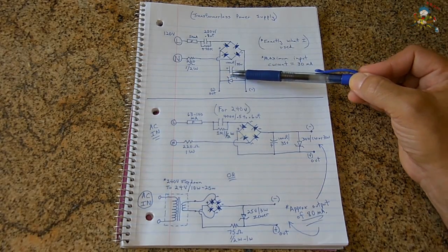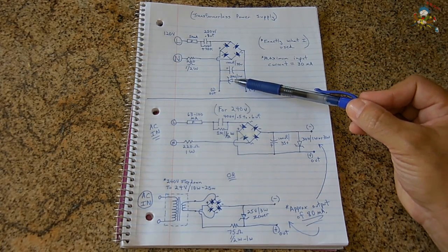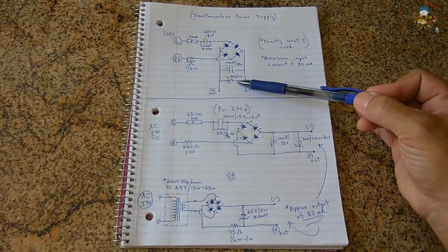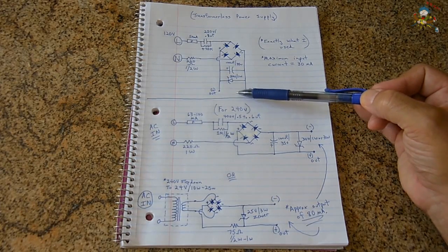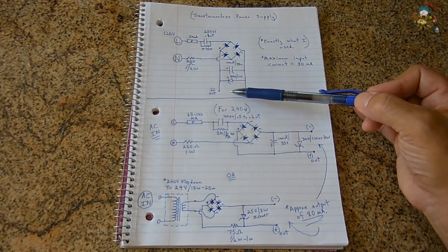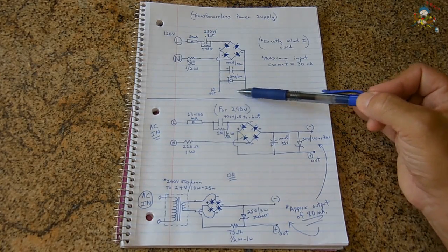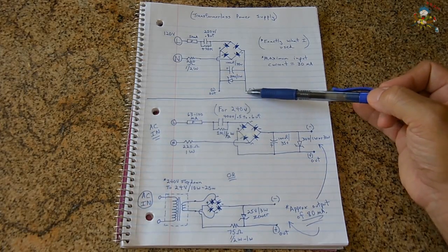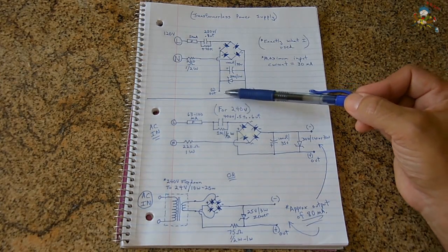Positive comes down, and that goes into a 100 microfarad 35 volt electrolytic capacitor, and that's to smooth out all the ripples. And I also added a 30 volt 1 watt Zener diode. You really are not going to be using that diode for the simple fact that the circuit is connected to the output at all times when it's turned on or turned off. I used it just to ensure that in the event that there's a problem with the LED strip light, the voltage will never rise above 30 volts across the output. Once the LED strip is connected, and if you have it at full brightness with the potentiometer, this will be probably around 24.5 to 25 volts across the output.